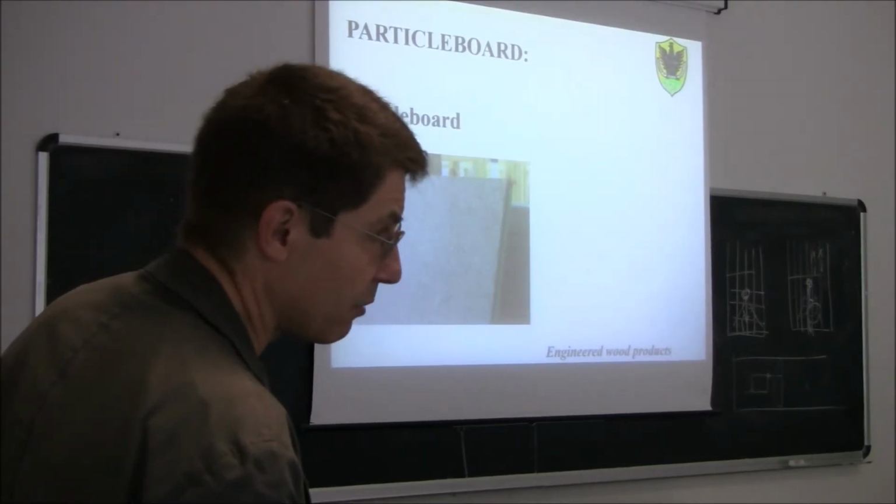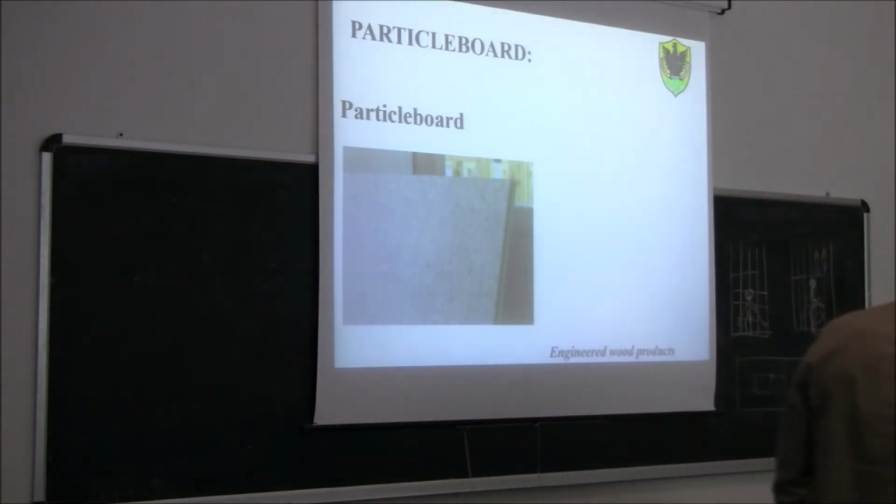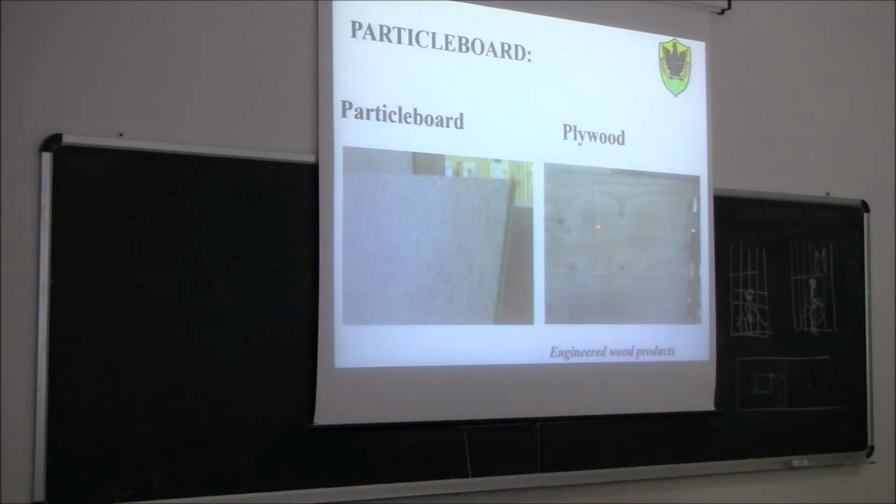I would say that we should never use particle boards in our construction. I know in England, also in New Zealand, they are used for the flooring, but I would say in Italy, I wouldn't use this kind of flooring because it's low quality. And this is plywood. Much better to use plywood than particle board. It costs more, but the properties are much better.